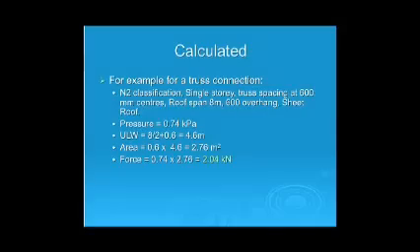So here's the information I was given. N2, single story, truss spacing 600 centres, roof span 8 metres, 600 overhang, sheet roof. So there's a couple of critical bits of information there. First of all, N2 and sheet roof are the critical parts of it.